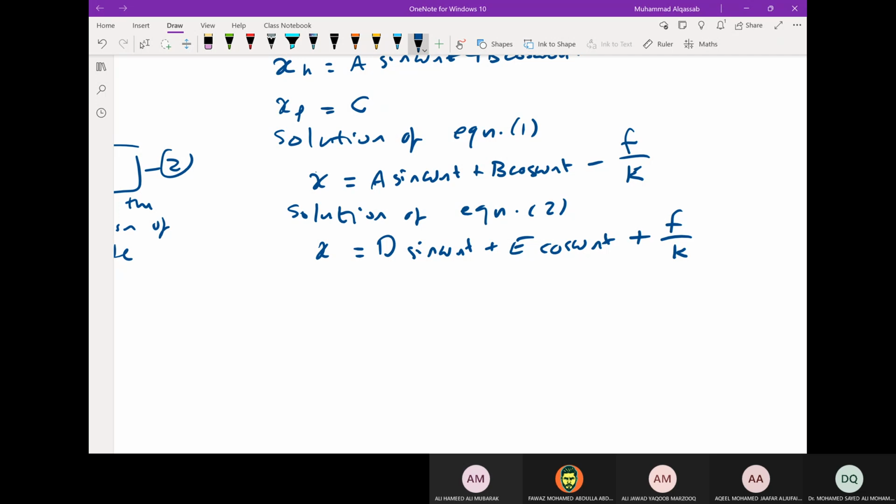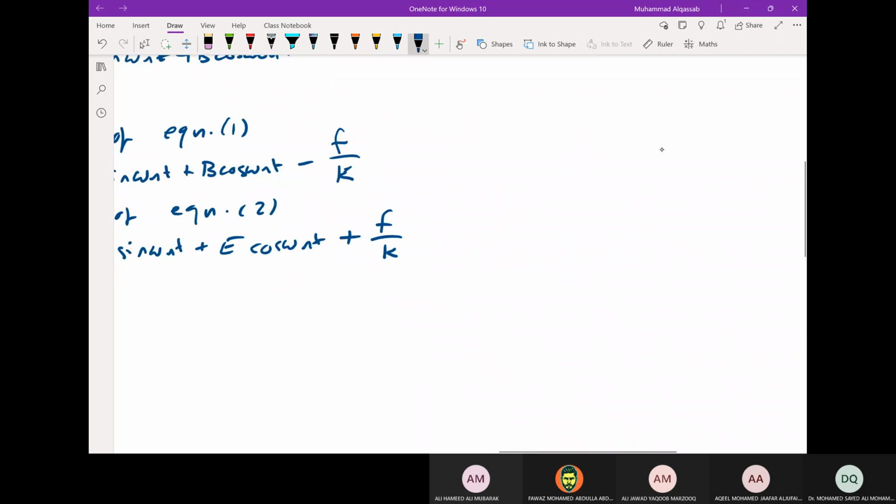So what you do is multiply F, which is equal to mu times N, by the sign of x dot. The sign of x dot is a function you can create yourself as well, equal to x dot divided by the magnitude of x dot.